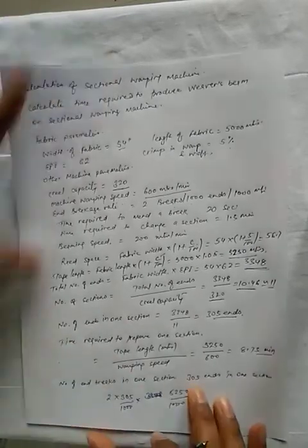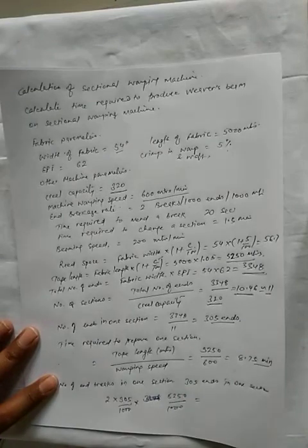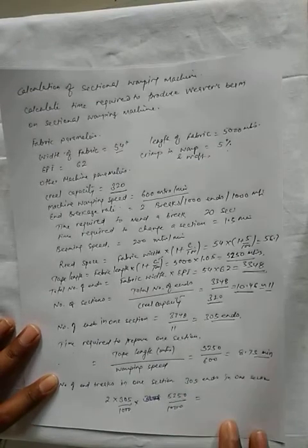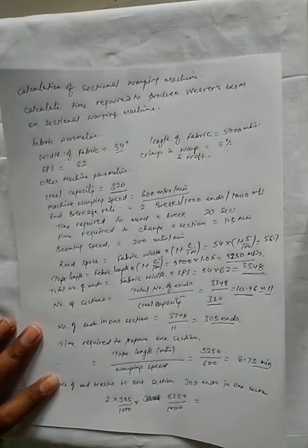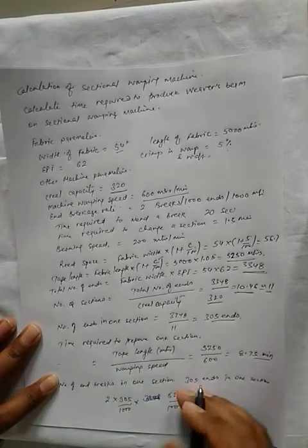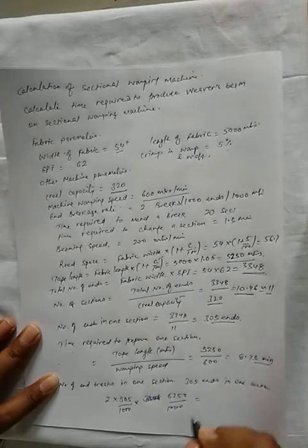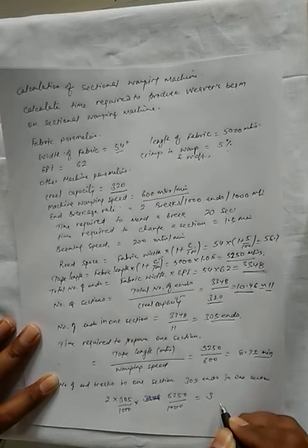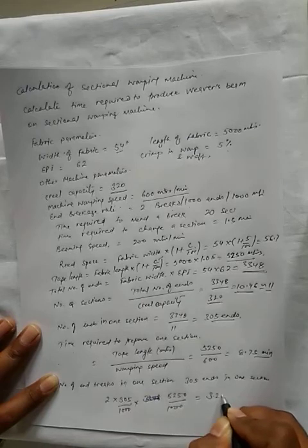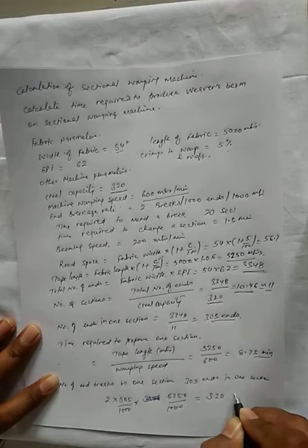This will give us the total number of end breaks during one section. So that is 2 multiplied by 305 multiplied by 5250 divided by 1000 divided by 1000. So this comes to 3.20 breaks